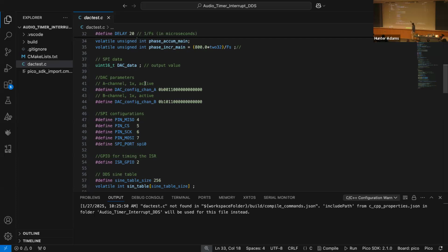So these variables, as we'll see, are updated in an interrupt service routine. And so we want them to be volatile because if our threads, our main programming, are using those variables, and then they get interrupted by an interrupt service routine which modifies them, when we come back to our main program, our main application code, we want it to use the most updated value. And so that's a way of telling the compiler, hey, this could change at any time. Please go get it every time you use it.